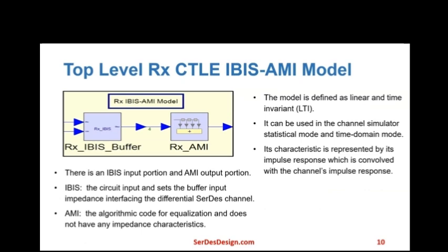The model discussed here is defined as linear and time invariant. It can be used in the channel simulator statistical mode and in the time domain mode. Its characteristic is represented by its impulse response, which is convolved with the channel impulse response.